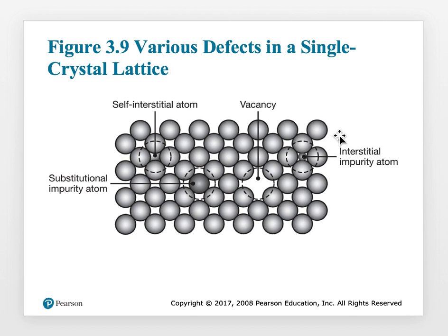See, the other way would be you have another type of atom that is inside the gap of this crystalline lattice. So you are creating internal stresses between those atoms, and then they will start being able to move from one location to another.